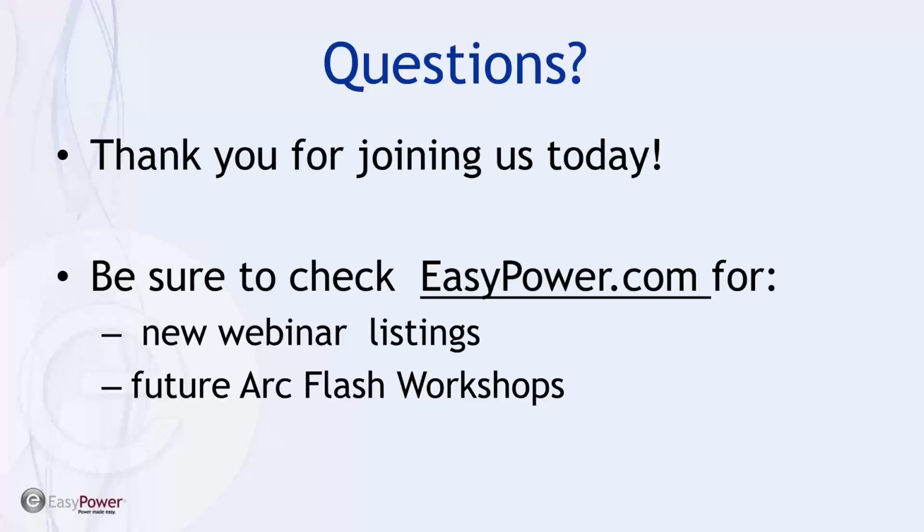Oh, I'm sorry, Diana, you had a follow-up there as well. Delete the equipment in the scenario. If you delete equipment in a scenario, that shouldn't give you an error unless maybe you've made changes to it. I'd have to check on that. It might flag it as, hey, this no longer exists in the scenario, I can't make that change. If you made a change to a breaker or a utility and then deleted it from that scenario, it might throw you a warning.